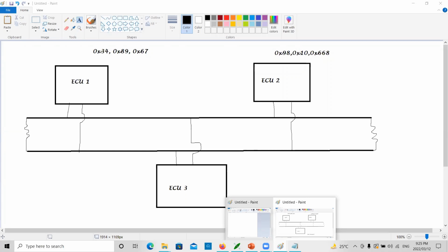If it is the lowest speed, they call it LS CAN. If it is a 250 kbps group, they call it mid speed CAN. If it is 500 kbps, they call it high speed CAN. In a CAN bus, if you have 10 nodes, all 10 nodes should operate at the same baud rate. There cannot be different baud rates. Otherwise, communication failure will happen. They cannot exchange information; you will find only error frames. That's why they have more buses.